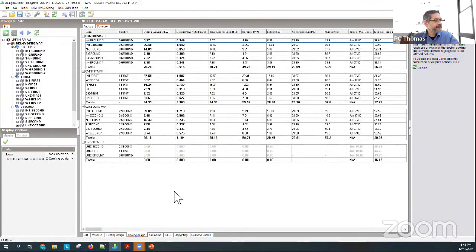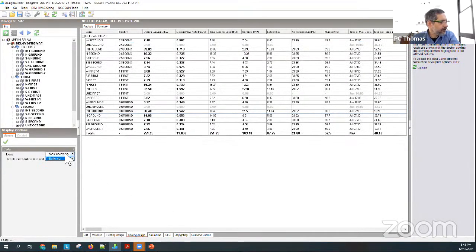In the summary, you can see here, the first thing I've done is I put this on what's called non-coincident and building level, okay? If you look at the zones, you can see that I've got 3 unconditioned zones. So it's not calculating the loads for those zones, but it is taking the heat load that goes from that unconditioned zone to the next zone that is conditioned. From your model, it works that out.